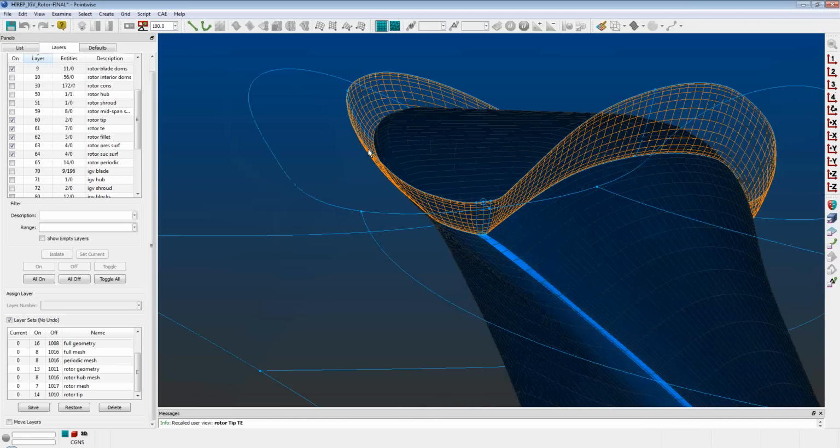The orange meshes you see here are the boundaries of the block in the tip gap region, and you can see how I have them bowed out to avoid the pinching of the edges of the round. If I ran these grid curves straight up from the round all the way up to the shroud, due to the nature of the round, we'd have some pretty nasty pinching.